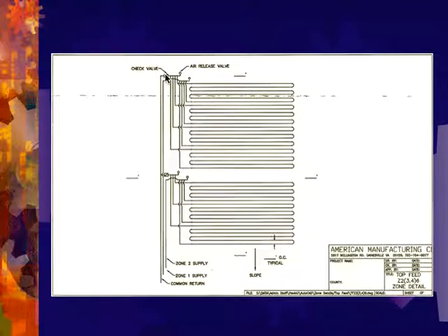Now this check valve can actually be moved in location close to this one, but it still needs to be in a position where water that's dosed to this zone cannot backfeed from this flush manifold into this flush manifold. So in other words, water can only leave the manifold and go to the flush line, not from the flush line back into the flush manifold.